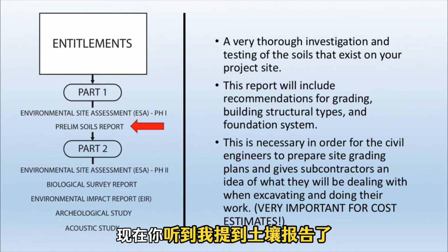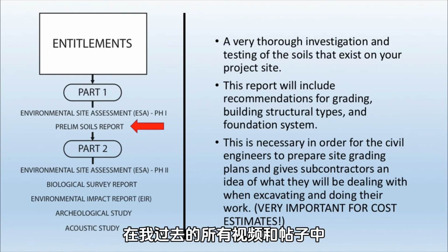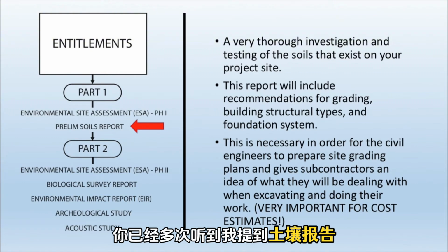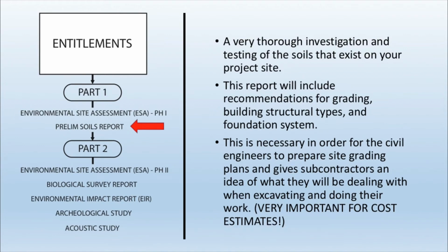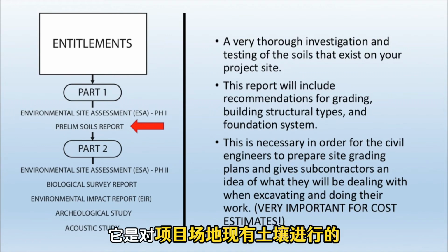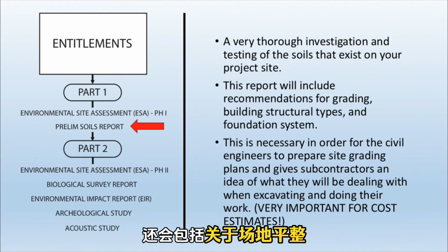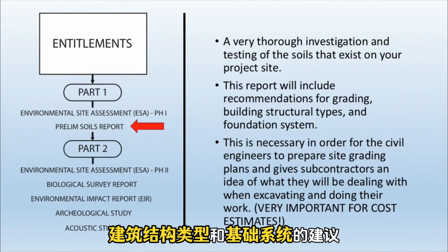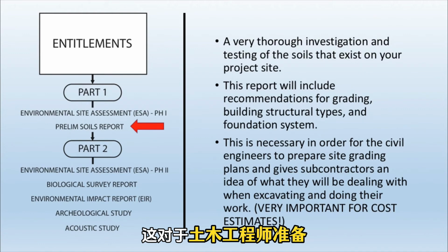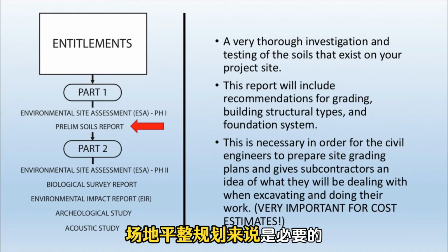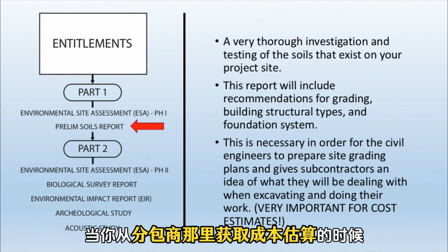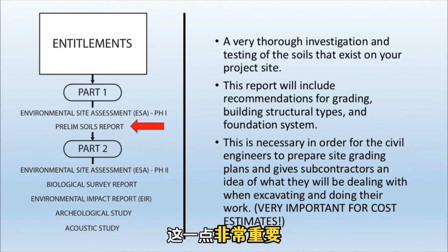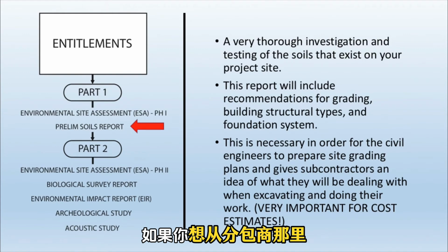Now, you've heard me mention the soils report multiple times in all my past videos and posts, because again, your soils report is hugely important, and it becomes a Bible for your project and instructions for you and all your subcontractors. It's a very thorough investigation and testing of the soils that exist on your project site. This report will also include recommendations for grading, building structural types, and foundation systems. This is necessary in order for the civil engineers to prepare site grading plans, and it gives subcontractors an idea of what they will be dealing with when excavating and doing their work, which is very important when you're also getting cost estimates from your subcontractors. If you need accurate numbers from your subcontractors for costs, they must have the soils report.